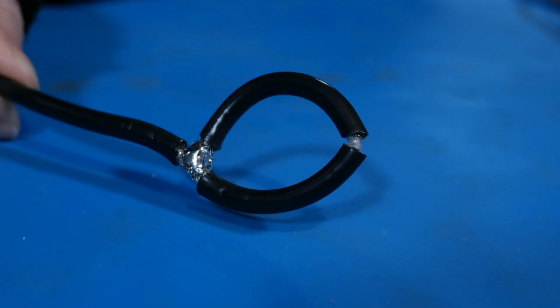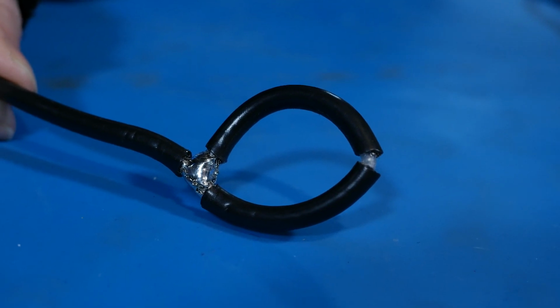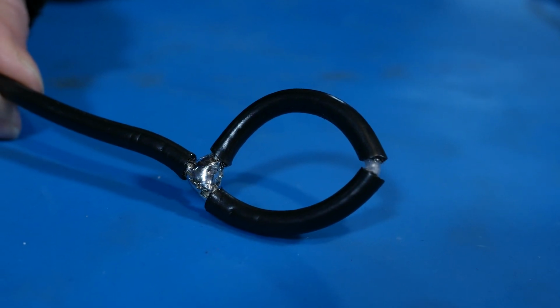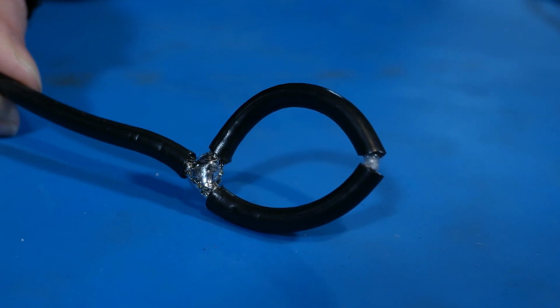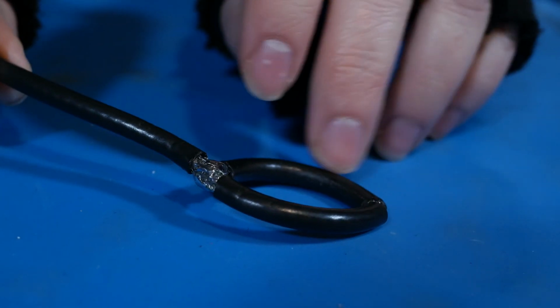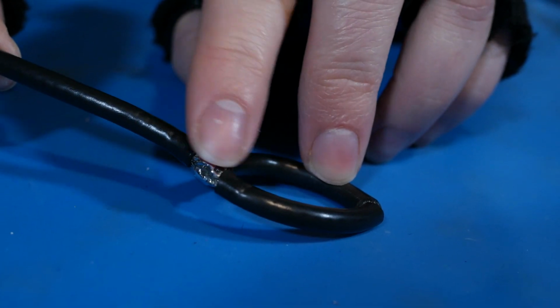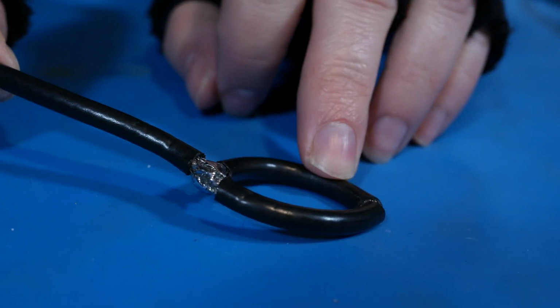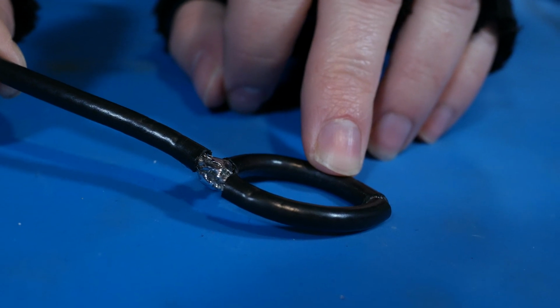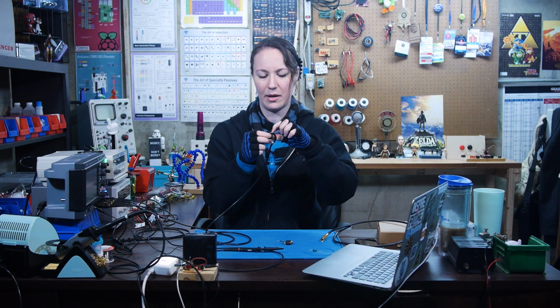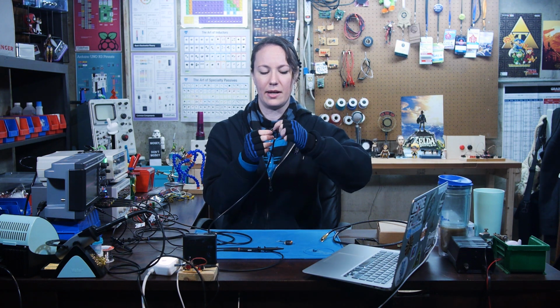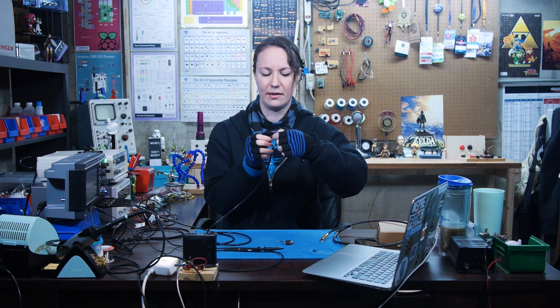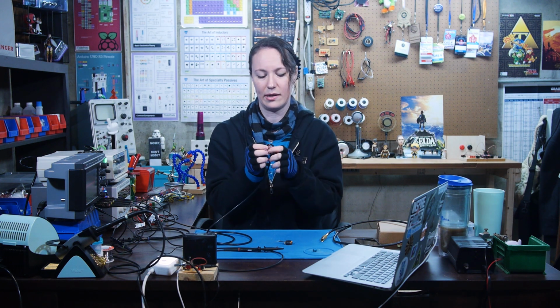And then, yeah, so mine did not have a solid core. It was actually stranded, so it was a little tricky, but you want to make sure that you solder the core and the shielding braid over here, so you've got to break that and remove some of the exterior cover. And then here, I want to make sure that I removed all of the braid, but I left the insulator and the solid core wire, the core is still in there. So that's what you want yours to look like. This is not the best quality one, but it's going to work.